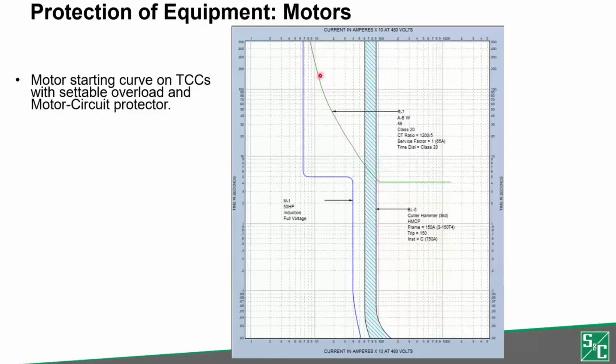So it's your motor overload, which is up here in this green curve, and that comes in different classes. This one, typical class 20, there's class 15, 10, and that depends on just what the shape of this curve is. And then that is set typically 125% over the full load amp of the motor. You may change it depending on your application. You could go off of that previous table we looked at.